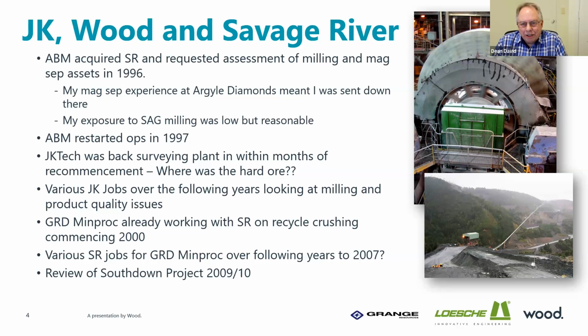And ABM restarted their operations in 1997. And then we were back very soon surveying the plant, mainly because it wasn't behaving as it was thought it would, because we were told it shut down because of hard ore, and the ore they started mining on was very, very, very soft. I think we measured about a 600% recirculating load of pebbles. So there was a few things to do with that circuit to get it going. We did find the hard ore, but it was nowhere near where they were planning to mine for about 5 years.